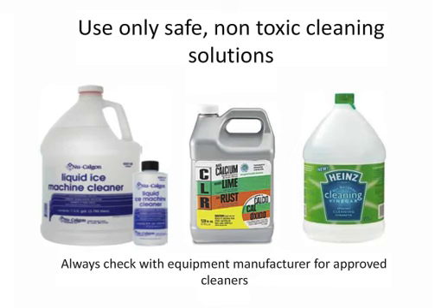So what do we do when we need to service that heat exchanger? Well, use only safe, non-toxic cleaning solutions, and always check with the equipment manufacturer to make sure they approve of it. What are some options? Well, I included a few here for you. On the far right, you can see just vinegar. Vinegar is typically used to start to descale and delime things.